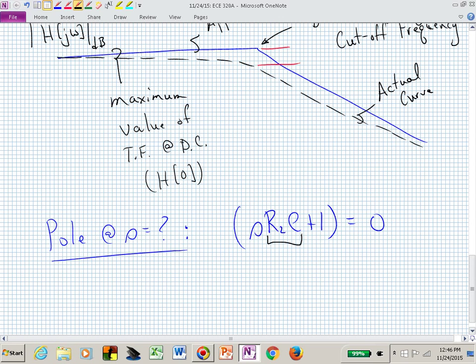S is a frequency, so what do we know that term that scales frequency must equal? So frequency is 1 over seconds, so this must be some time, and that's actually our time constant, tau, R sub 2 C.